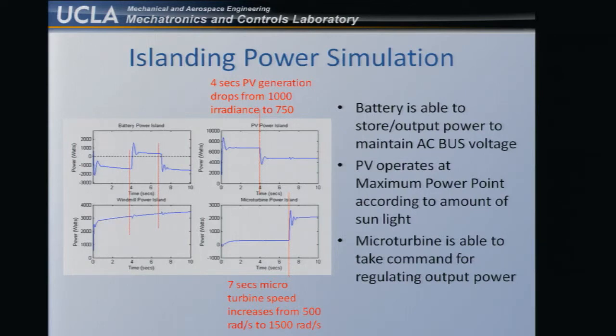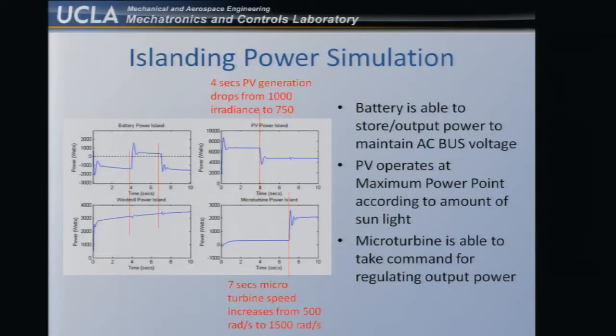But we found that the transient is still important, and feedback control alone won't be sufficient. It has to have some forecasting, so that when there's a switch, the management would tell the DER, I'm going to switch in the next 10 seconds, exactly when, and this would be able to reduce its spikes.